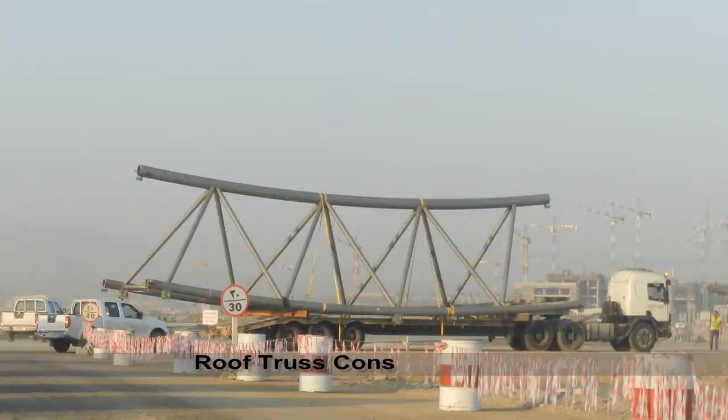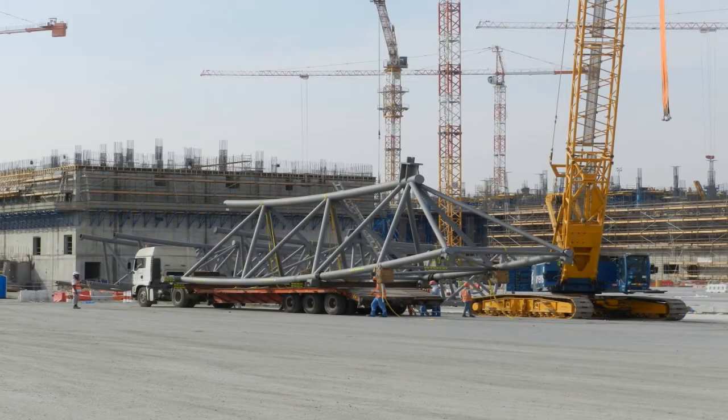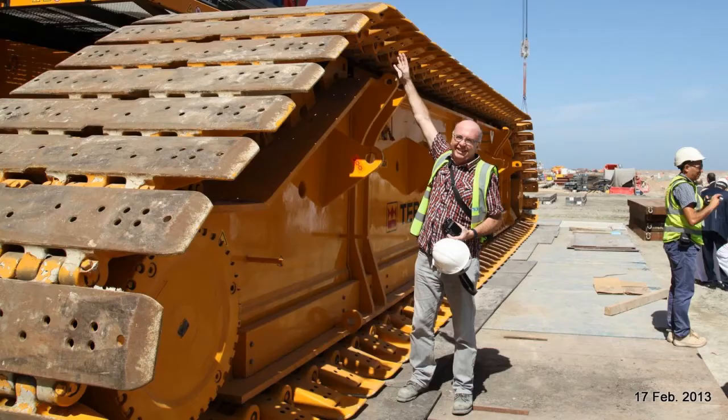Roof trusses for airport terminal building. The 200-ton weight roof trusses are delivered to site in sections by ship and trucks. The trusses are assembled on trestles and are lifted into position by a crawler crane with a counterweight wagon.